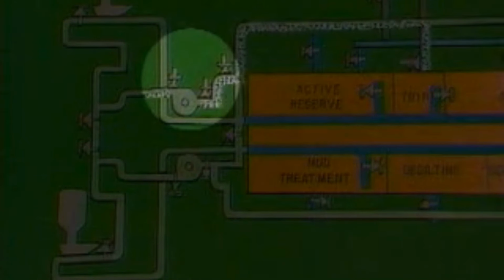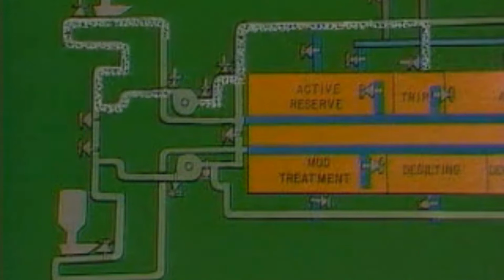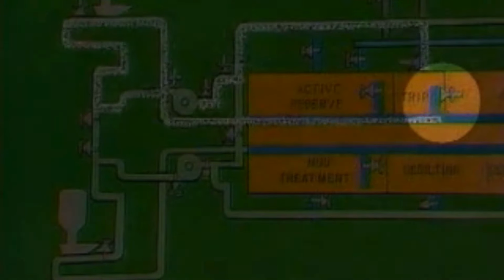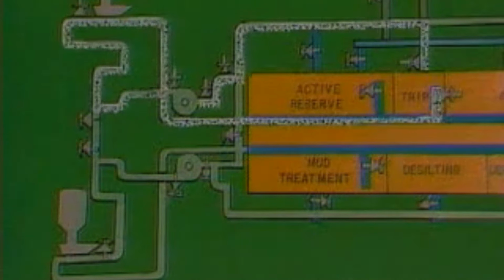Then, open the valve at the suction side of the mud mix pump. Open the output valve. Then locate the line that goes to the mud jets. Open that valve. On the output side of the mud jet, open the valve that flows mud back to the kill tank. It's that simple, on paper. Now let's watch someone do the same thing on our system.